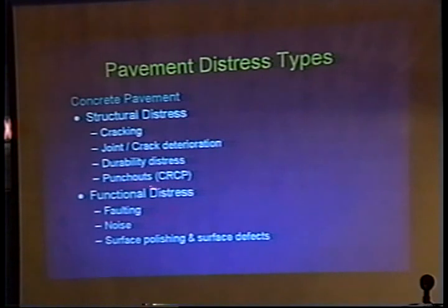Functional types of distress, we'll talk about. Faulting, where you have one side of the crack or one side of the slab higher than the other, causing a fault. Noise problems, if you do have that, possible surface polishing or incidental surface defects.